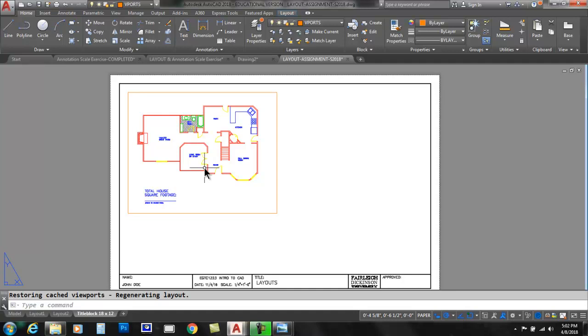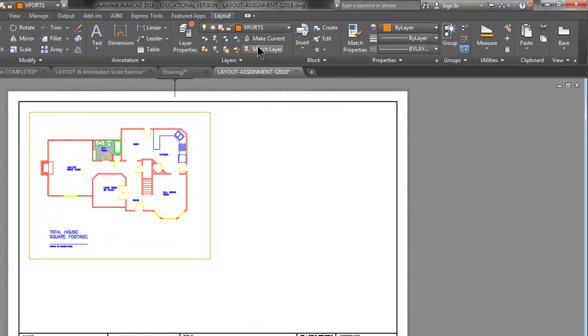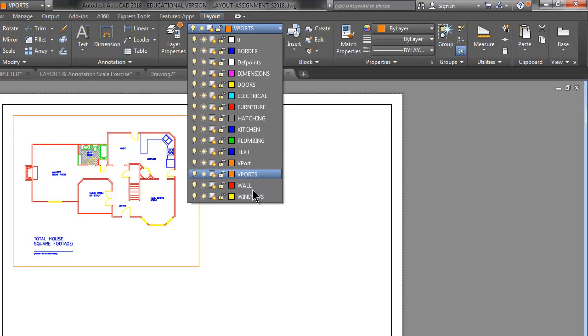Okay, so go down the list. You're going to switch to the Layout tab containing your title block and prepare new viewports. You're going to create the viewports with appropriate size, then scale the geometry within it. Include the connecting lines, right? So I want to see this as a circle, and I'm going to have to create a layer for phantom. I don't believe there is one in here. There's nothing phantom. So you have to create a layer for phantom.